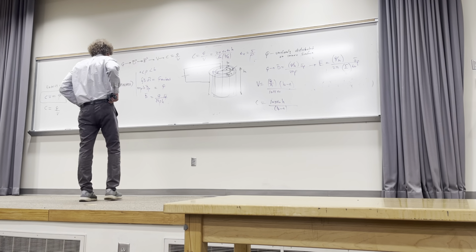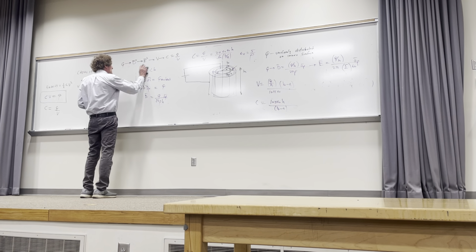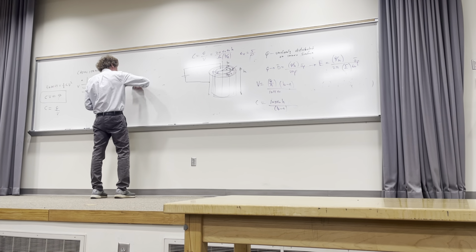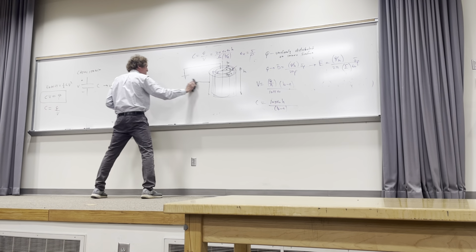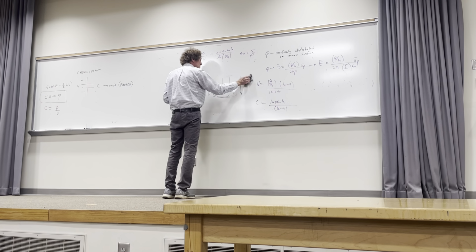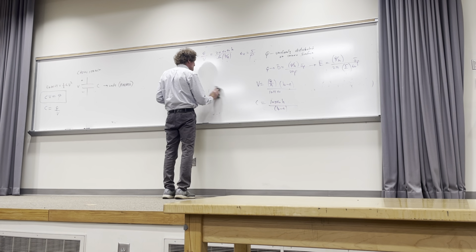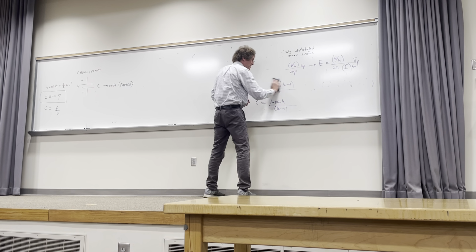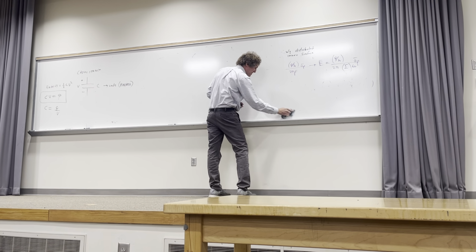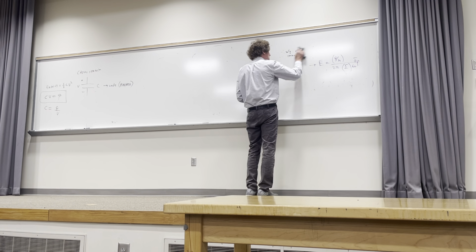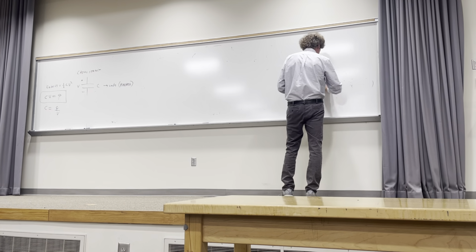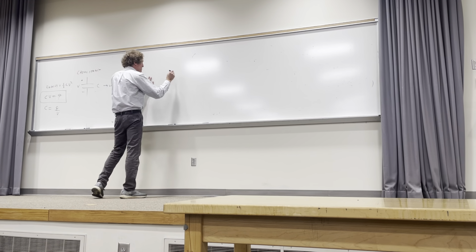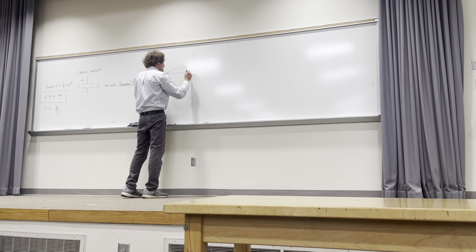Okay. The final one I'm going to do is the easiest in a sense, but it's the planar one. This is the one where I don't generally assume Q. I can do it that way, but I go backwards. I assume V and get E, and then from E I get D, and from D I get rho S, and I get Q, and then I get the capacitance. So I go backwards on this one, but you don't have to. So this is the parallel plate capacitor.